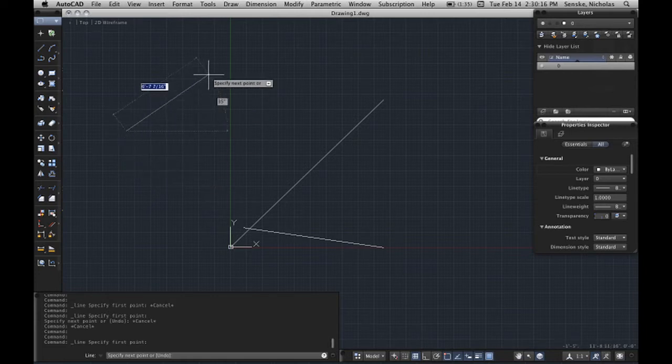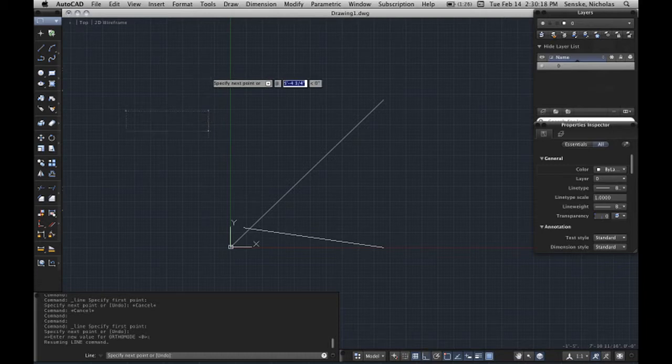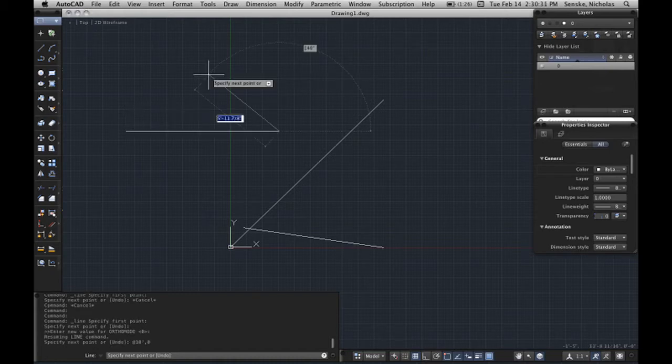What I can do is use the @ symbol, like the @ we use for email, where you hold down Shift and press 2. Then I can type in a coordinate. I can say the next point is going to be at 10, comma 0. That will draw a line from that point. Imagine this is now 0, 0, so this is 10, 0 from that point. It's the coordinate system relative to the point that I started. Does that make sense?